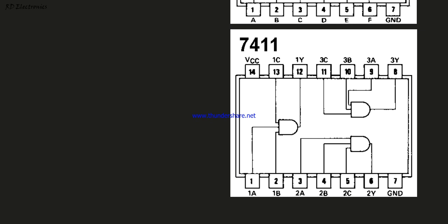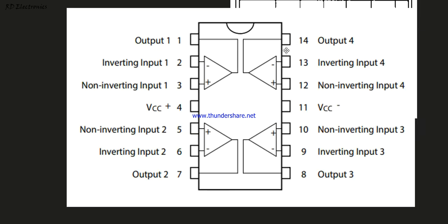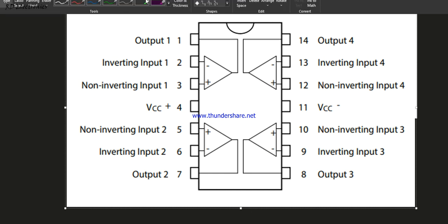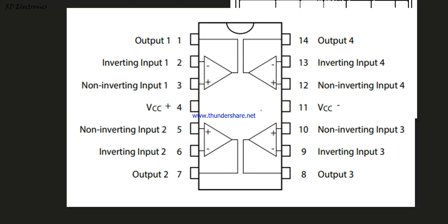This is also very important for detailed electronics applications. This IC is known as TL074. This is a quad operational amplifier, because 4 operational amplifiers are available, and the advantage of this IC is that it does not require any offset adjustment. Minus VCC is connected to minus 12 volt or minus 15 volt. This is plus VCC, plus 12 volt. These are the biasing voltages, and here 4 op-amps are connected. This is inverting, non-inverting and output, and so on.